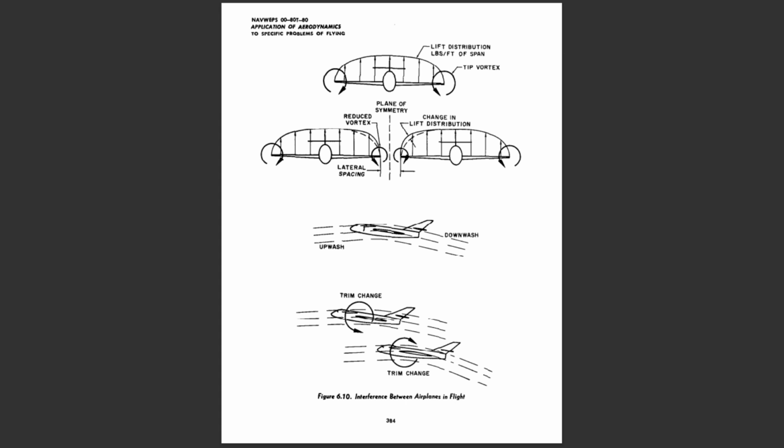This disturbance may provide the possibility of collision if other airplanes are in the vicinity and there is delay in control correction or overcontrol. If the wing tips are displaced in a fore and aft direction, the same effect exists, but generally it is of a lower magnitude. The magnitude of the interference effect due to lateral separation of the wing tips depends on the proximity of the wing tips and the extent of induced flow. This implies that the interference would be greatest when the tips are very close and the airplanes are operating at high lift coefficients. An interesting ramification of this effect is that several airplanes in line abreast with the wing tips quite close will experience a reduction in induced drag.